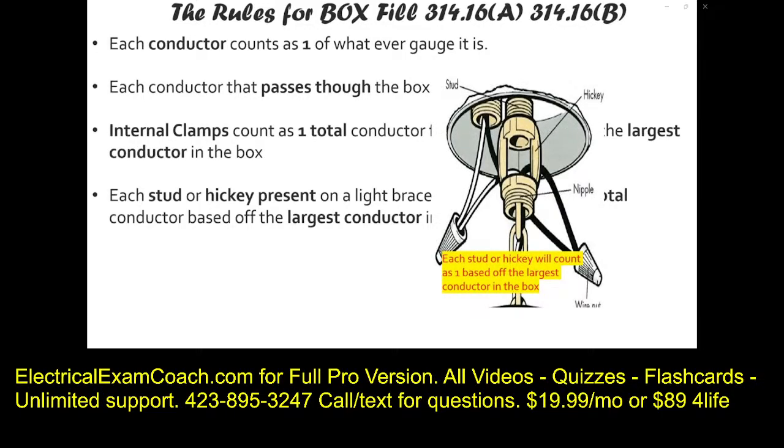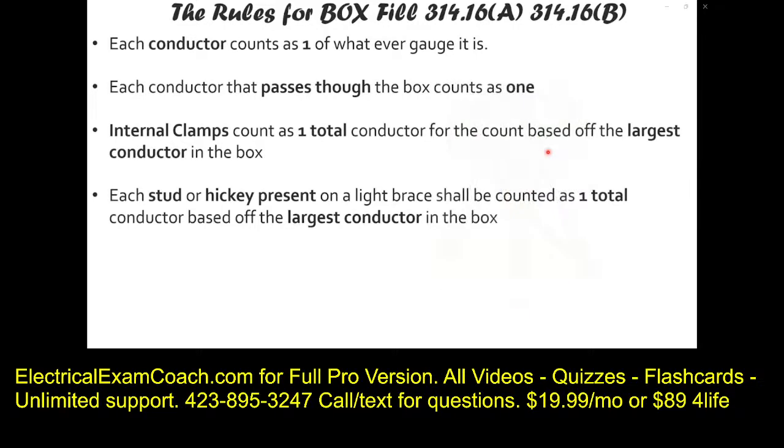Imagine that we're hanging a chandelier. This we would call the stud or the nipple. Or, this would be the nipple. But they're calling this the stud and this a hickey. And they still use this terminology on exams today, so you definitely need to understand. In this scenario here, in this picture, the stud would count as 1 of whatever gauge was in the box that was the largest, and the hickey would count as 1 of whatever gauge was in the box that is the largest. And we're going to do lots of practice, so don't worry about it.